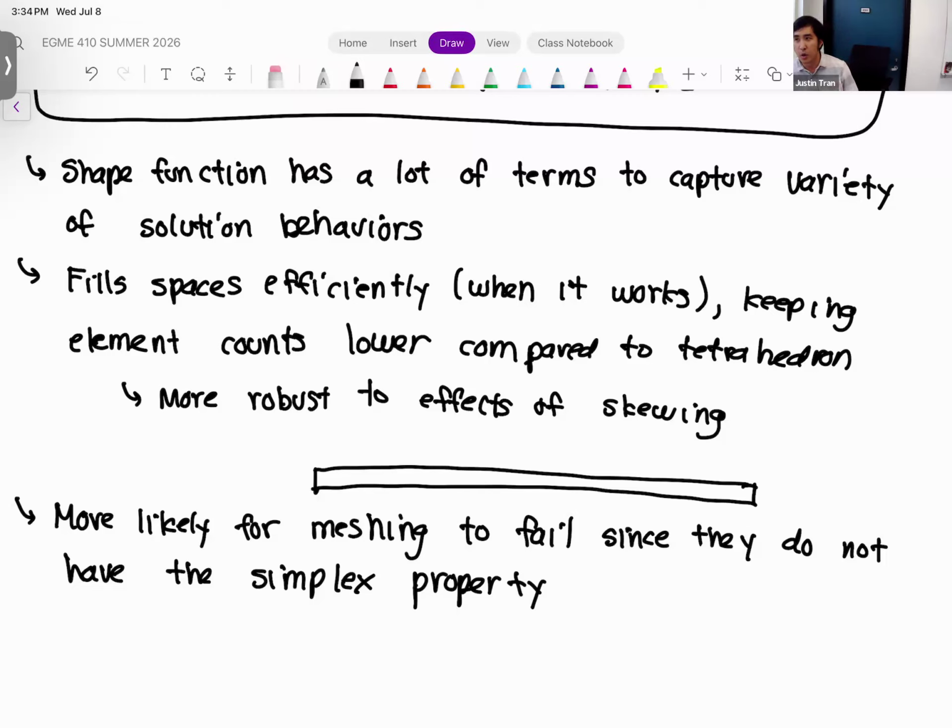Yeah, it's a good question. I would say, if the meshing is not that expensive, in that you can get a mesh within a minute or two, which for everything that we're going to do in this class falls into that category, there's no harm in trying to get a complex mesh. So use hexahedron elements, use quadratic elements, and just see where it takes you. Because worst case, if the meshing does fail, you'll find out within 30 seconds.